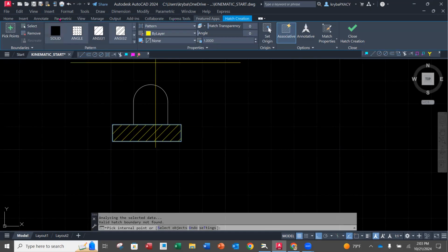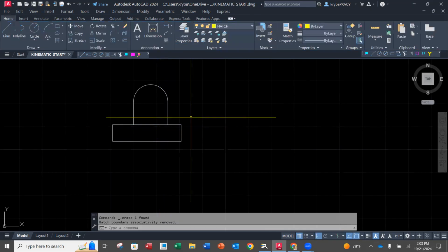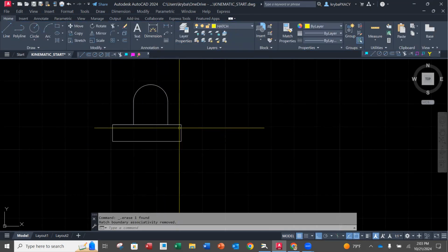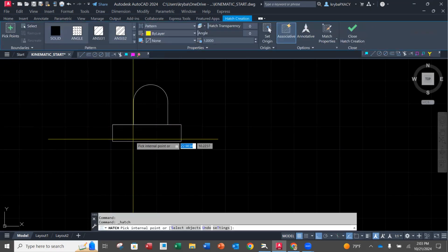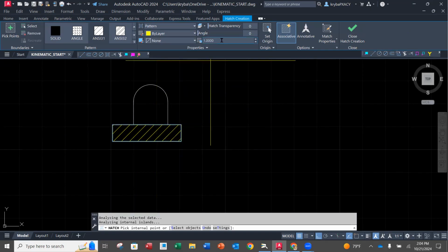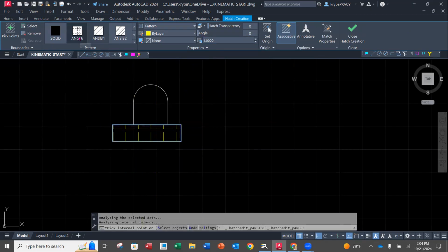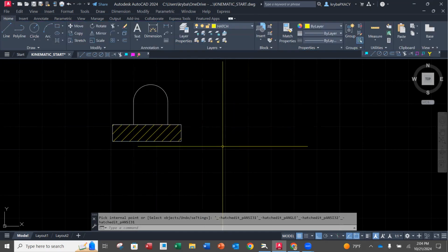So to cross hatch, I'm going to close this out and get rid of mine right here. Delete. So you have to have a closed rectangle in this case. There's the hatch right here in the draw menu. Do you see it? You're going to click on that and go into the inside and it should activate it. And then left click. Like I said, you can change the scale if you need to. It's ANSI 131. Don't use any fancy business. We're just going to use the regular ANSI 131. And then we're just going to hit close to accept it.